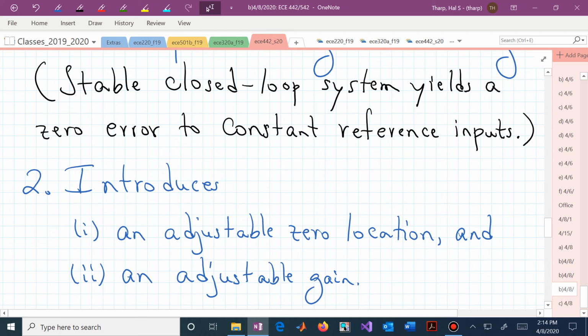Actually, you'll buy a PID controller, you would just set the derivative knob to 0. Now you adjust the proportional knob and the integral knob on that PID controller, and that adjustment is effectively allowing you to manipulate the 0 location in that transfer function of your PI controller.